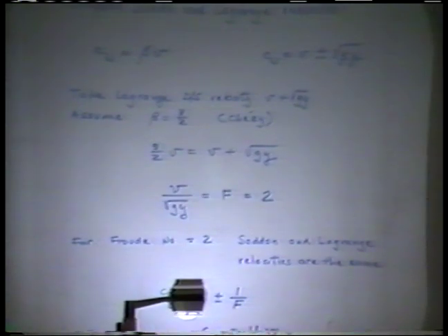And we can show it to ourselves, and I've done it, and we'll talk about this when we get there, that if you have a channel like this in which the wetted perimeter increases at the same rate as the area, the Froude number for instability is equal to infinity.